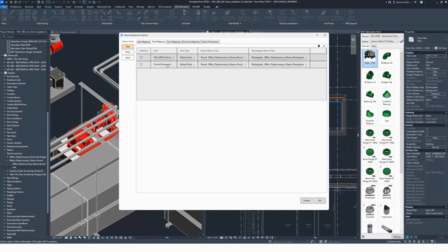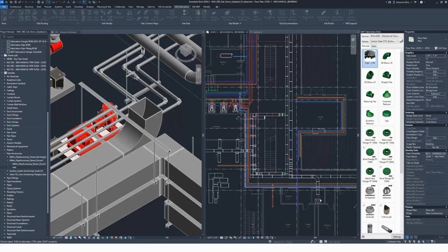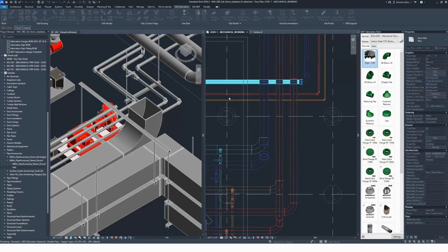I don't need anything fancy. But in that same model, when I hit a typical partition wall, which my architect told me is 1 hour fire rated, just place a Hilti sleeve instead. And now if we go in and start placing one of those down, it's as simple as choosing wall sleeves, an element to work with, finish. And Naviate's going to go ahead and find the intersection on that wall, place that sleeve against that wall, and we'll see that it's going to be that Hilti sleeve because that's a typical partition.